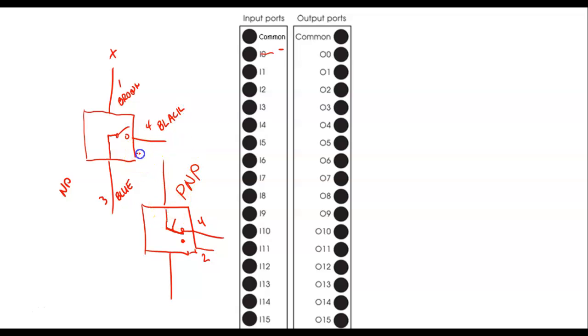And if we had a 2, then it would be white. So white would be the normally closed and black would be the normally open. So you've got a single pole double throw switch in a 4-wire sensor. We do have some over. None of ours, I don't think, are 4-wire sensors. I can't think of any that are 4-wire sensors.